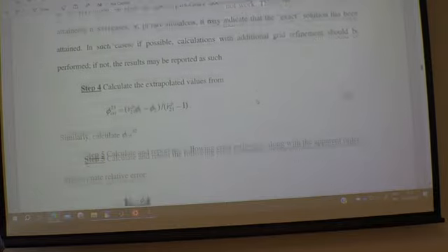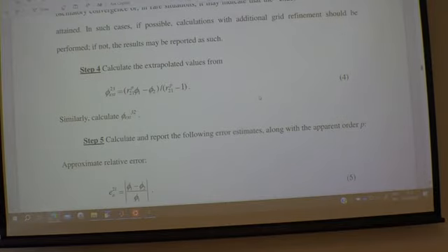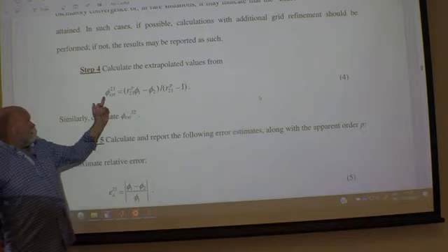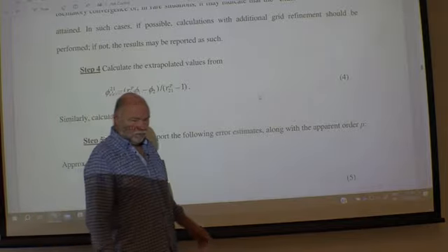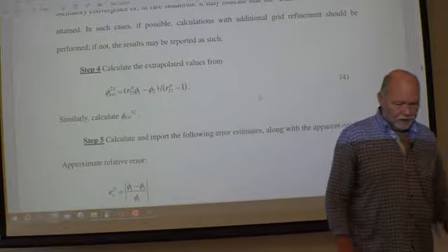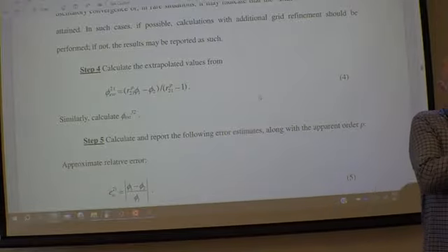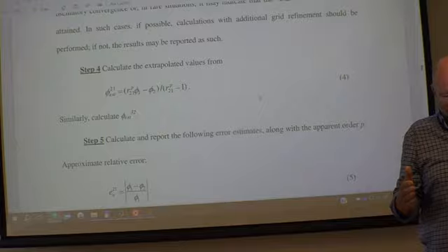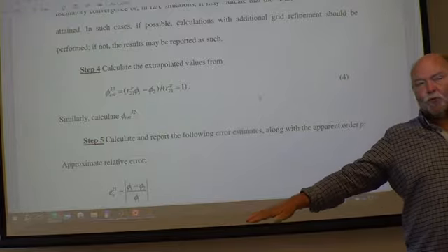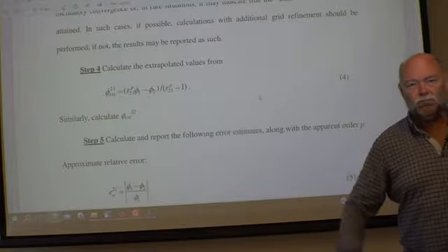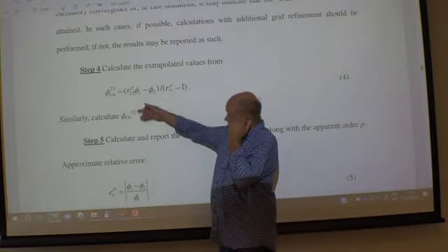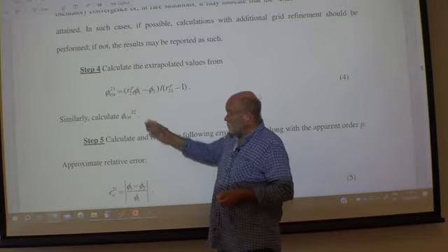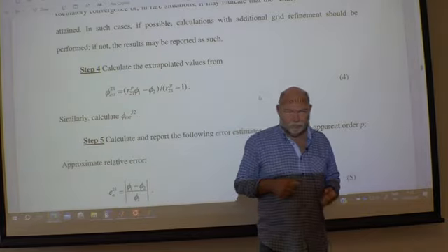Now, we can actually find extrapolated values. Extrapolation, as you should know, is highly illegal. We're not allowed to do that. So finding a solution with 3 meshes and then extrapolating, what would it be if I have an infinitely fine mesh? That's not allowed. We'll actually get an idea here, but don't use them.